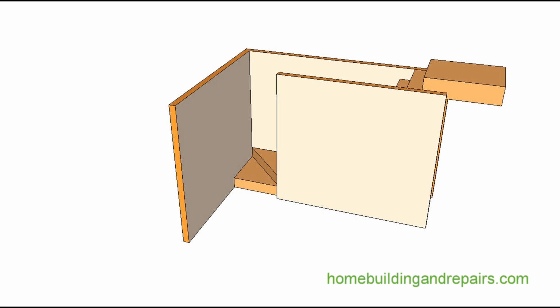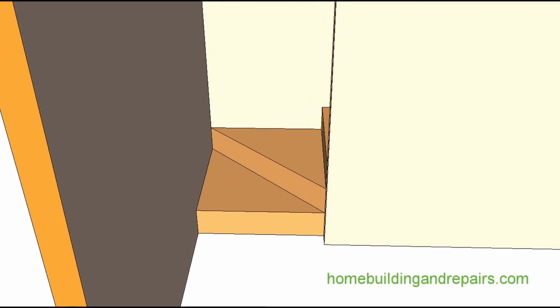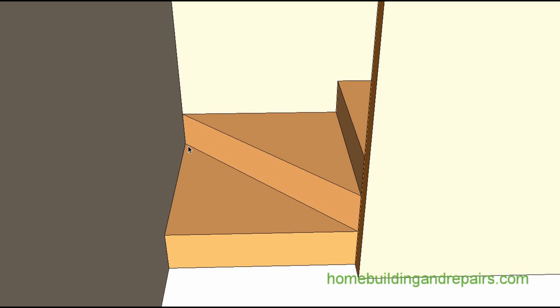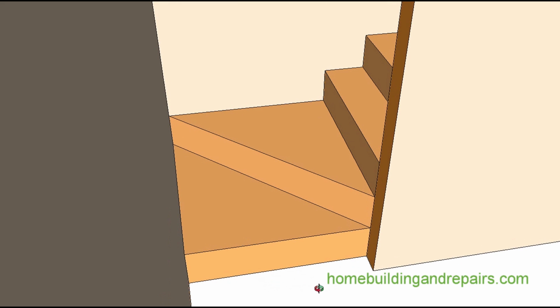Here's a common problem with this particular stairway, and this landing wouldn't meet local building codes today, but obviously did back in the 1970s when I first started putting stairs in. We did this all the time. Now the problem with this particular stairway is, not as much when you're walking up, but you can just imagine you're going to hug the narrower side. You're not going to walk over to the wider side, step up here, and then walk up the stairway. You're usually going to be hugging the inside of the stairway.